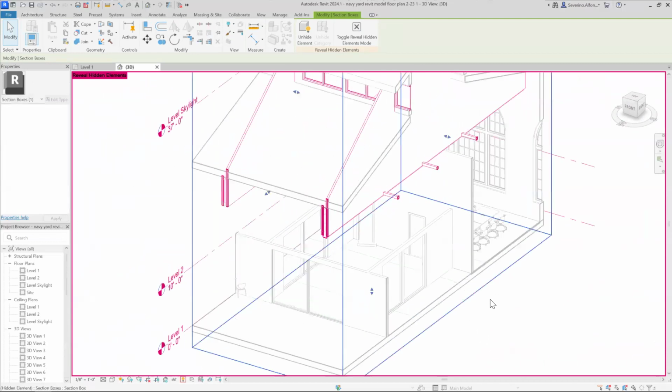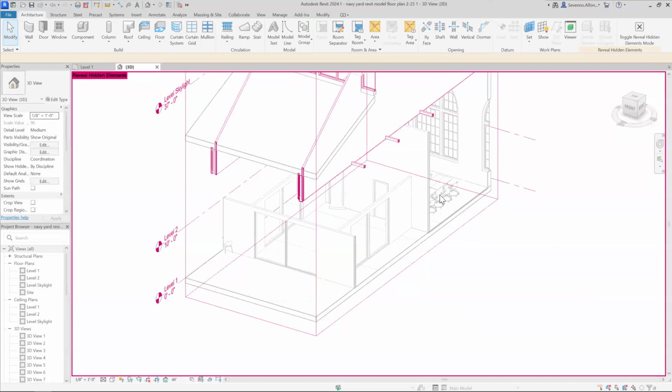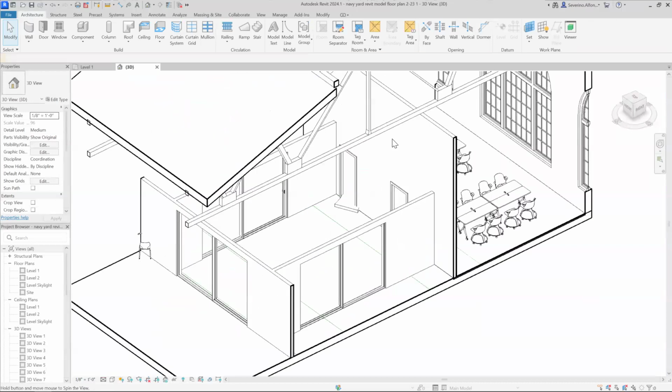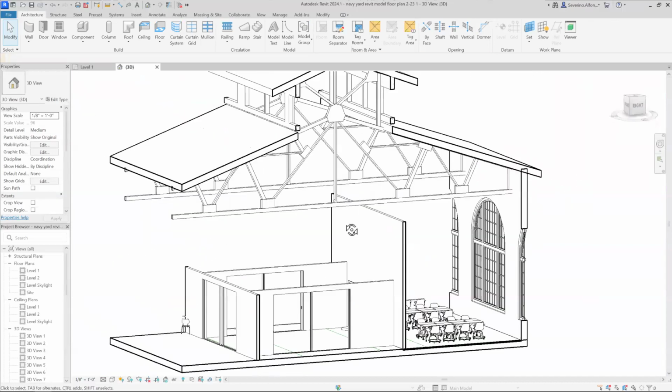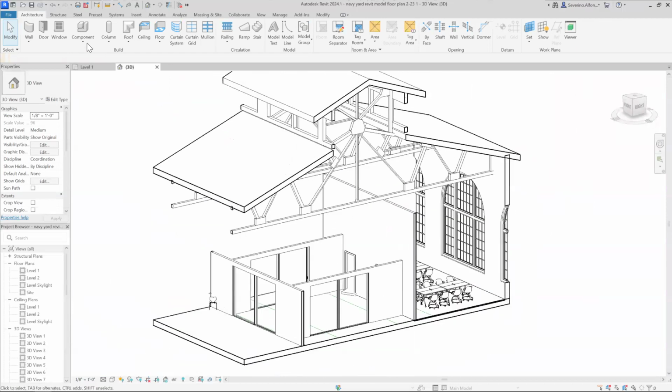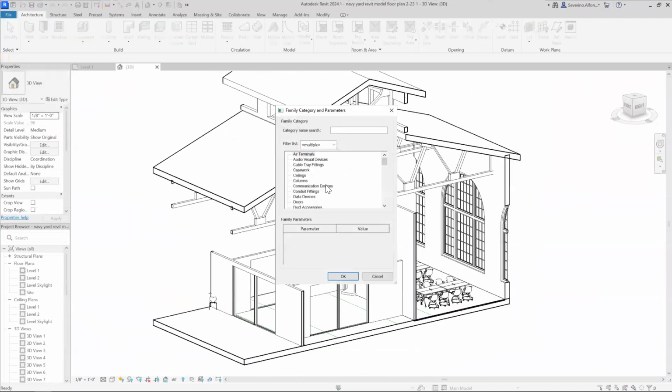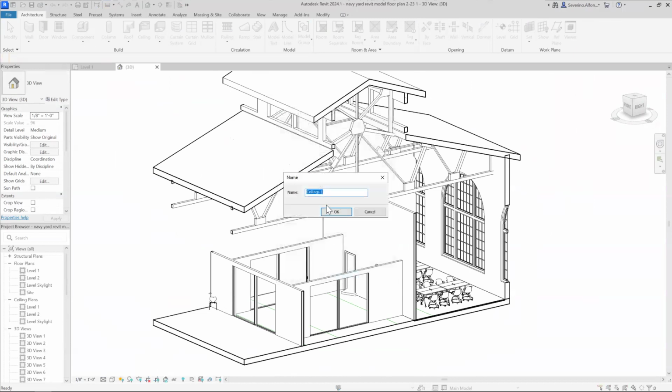And I mean, you can do it this way, or you can just do it many other ways. But okay, so we have this space. How do we start dealing with sections and so on? As I said, probably what we need to do is model in place as an option. I think maybe continue as a wall or ceiling component. Probably if it's a ceiling component, you will use the ceiling here. But if it's an extension of the wall, you can use walls, and you can keep them both under walls or under ceilings, because there's a little bit of a moment where things get confused depending on the angle, no? And you were going to call it, let's say, space.